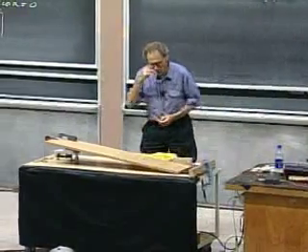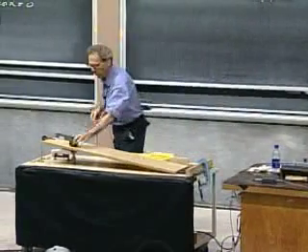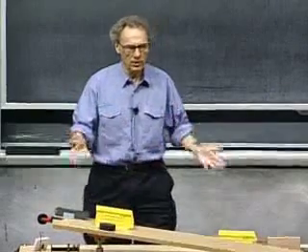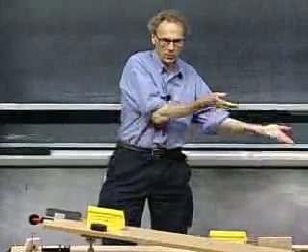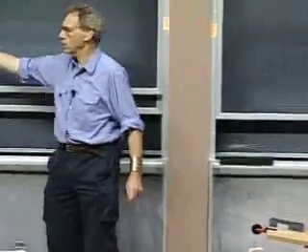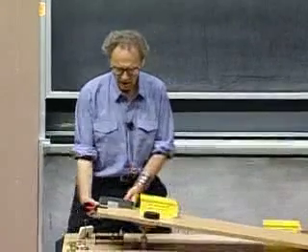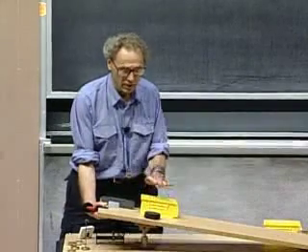The first thing I want to show you: I take a rubber puck and put it on this incline, and I have a plastic bin, which is quite smooth. It's immediately intuitive that the friction coefficient of this plastic bin will be lower than that of the rubber puck. So when I increase the angle, you expect that first the plastic bin will start to slide and then the rubber puck. If I gave you the angles at which that happened, you could calculate the two values for the friction coefficient, which I will not do now, but I will do later. All I want you to see is that this one will go earlier than that one.